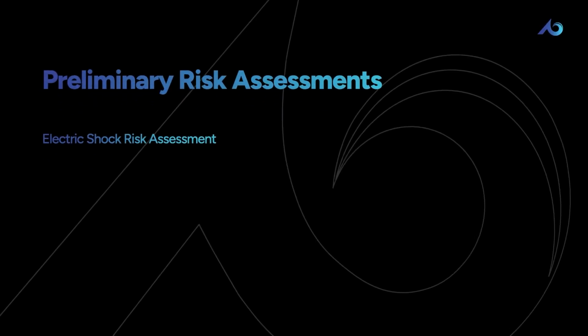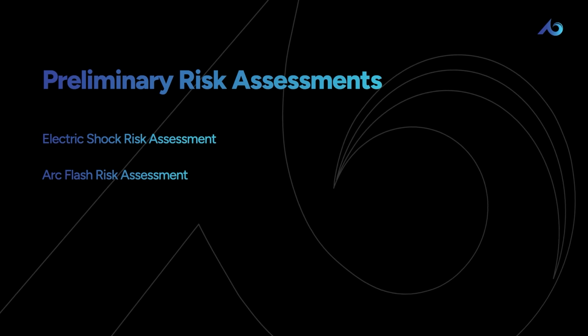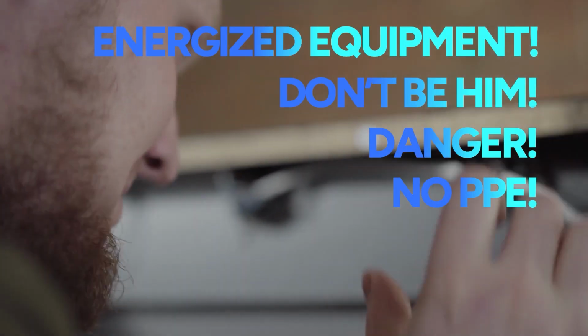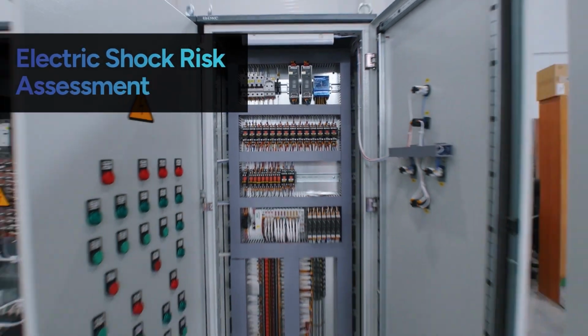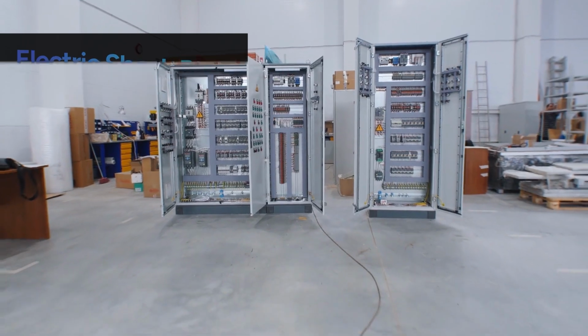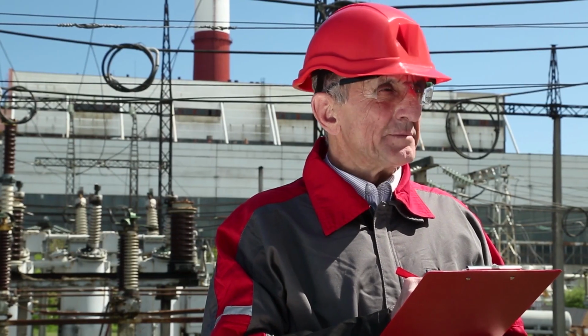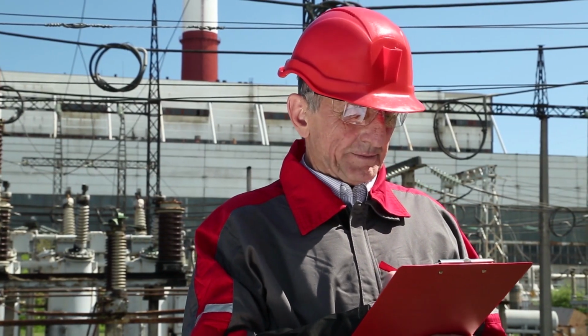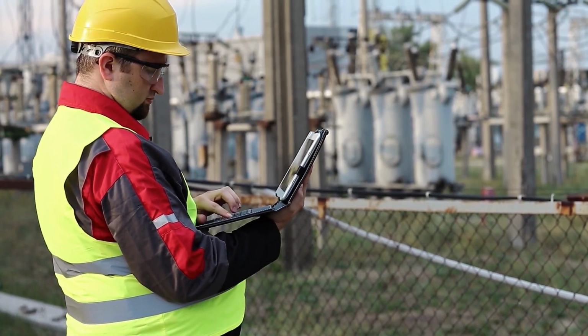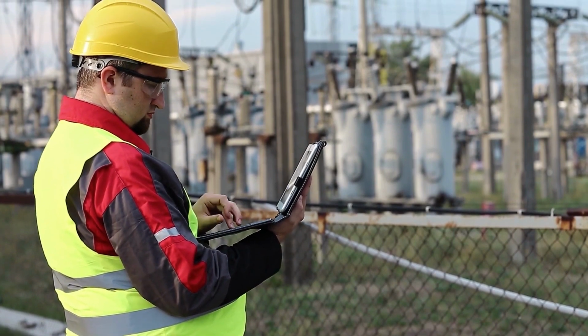The two assessments they'll need to conduct are an electric shock risk assessment and an arc flash risk assessment. Again, an electric shock is different from an arc flash, so the two are treated separately. An electric shock assessment focuses on identifying the risk of coming into direct contact with live electrical equipment. The assessment typically examines the voltage level and type of equipment in question. A qualified person can look at these factors and check the tables in NFPA 70E to determine the appropriate working